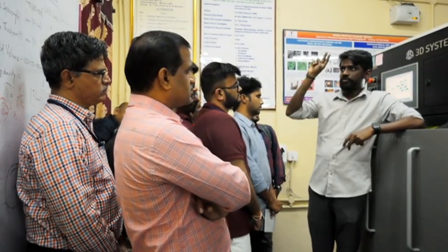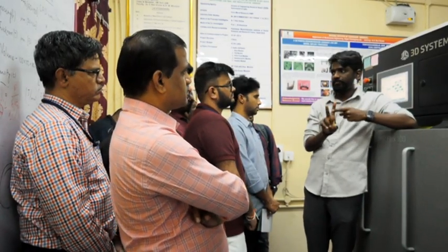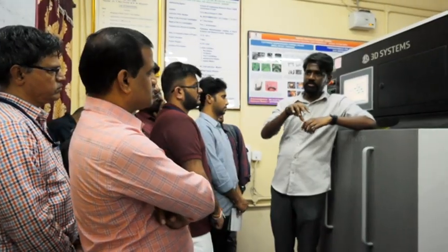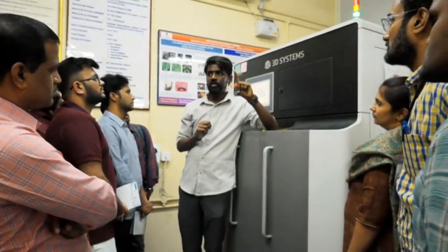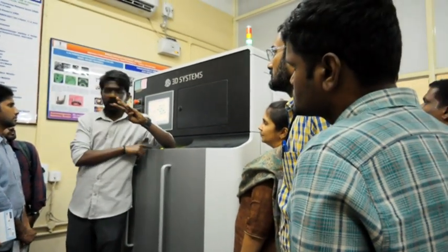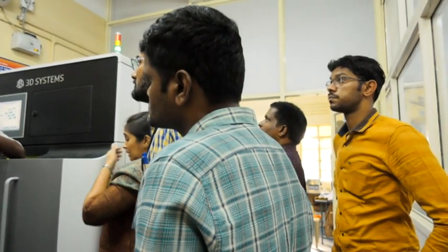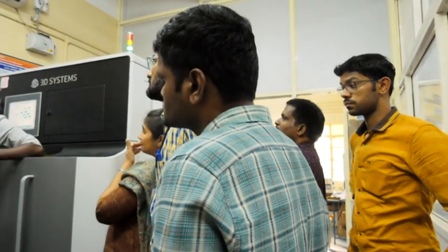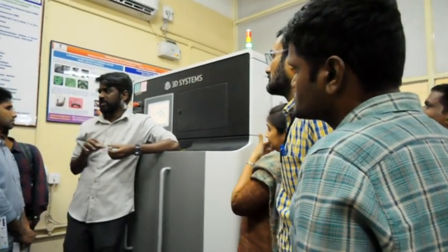There are two main pistons: the supply piston, followed by the center piston. In the supply piston, you have to load the powder. In this machine, we have four materials: aluminum, titanium, stainless steel, followed by cobalt chrome. Right now, I have already loaded 74 kg of precipitation hardening steel. And in previous sessions, Srikanth might have talked about the 3D Expert design, right?